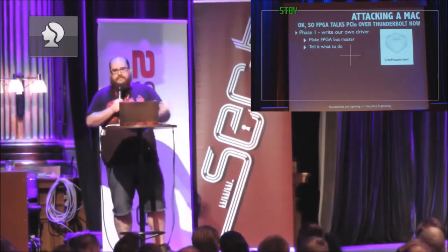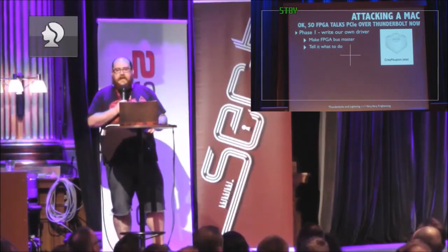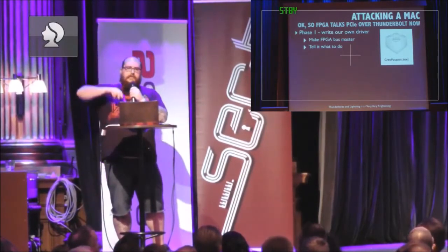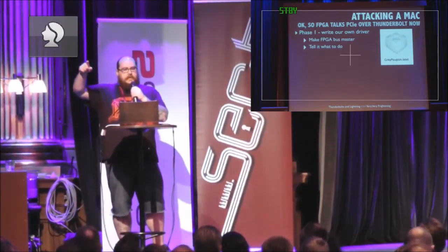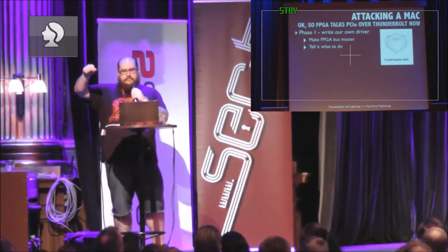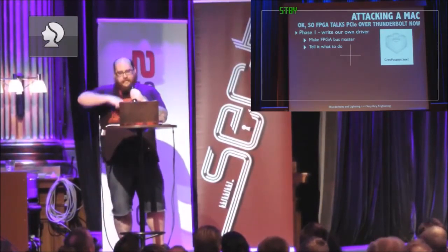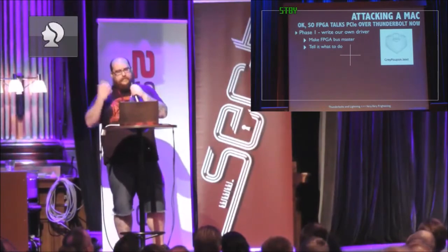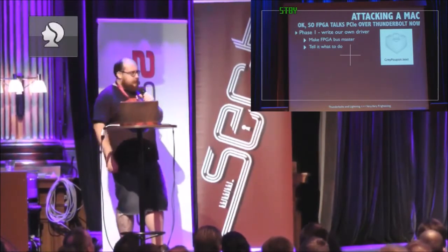So we just write to it over PCI Express, and say, write to a register that says do a DMA read at this address, and then put the result into this register, and then we'd read it back from our driver again and go, hey, cool, it worked, or no, it didn't work. Let's do all this debugging stuff in ChipScope.